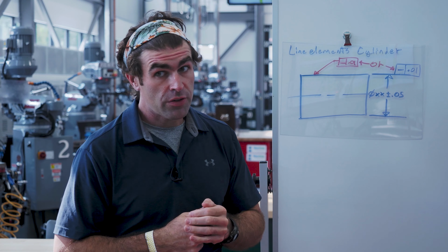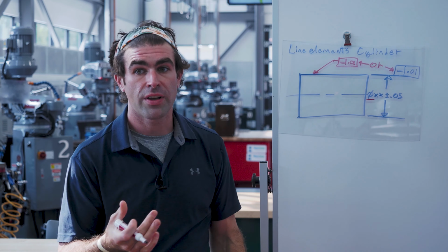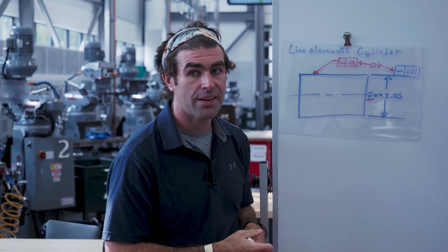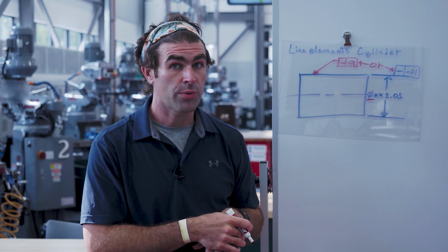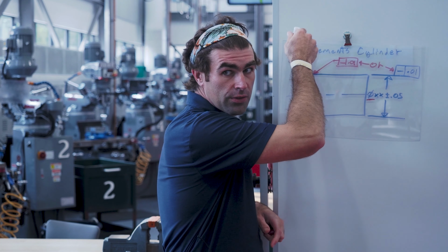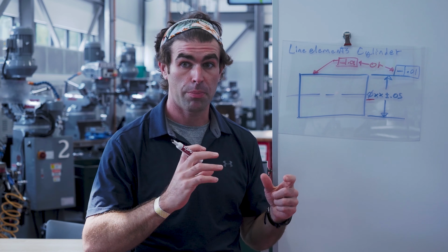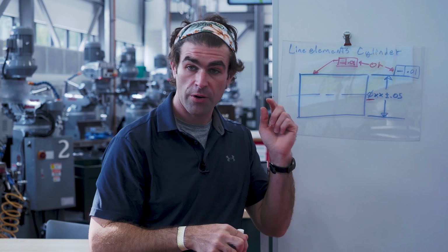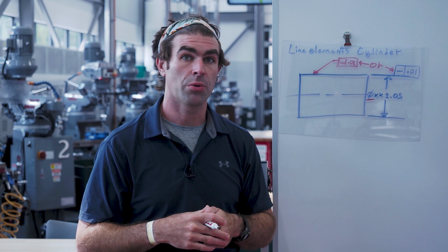So this is similar to our rectangle a second ago, but if you notice, we've got a diameter symbol in there. So this is a cylindrical part. We check the flatness in the same way. It's still got to be less than the size tolerance because we're refining it, but we can just run the indicator going in this direction. As long as it's within 10 thou, we're good. So if it's just a pin or a cylinder, you just check one, you roll it a little, check another, roll it, check another, and just keep going until you get less than 10 thou on each individual one.